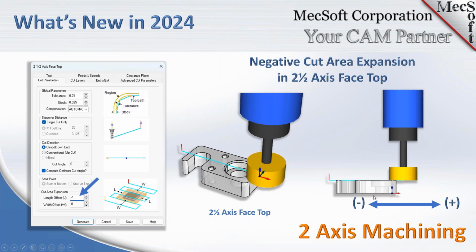Previously, the tool would go all the way past the part and clear the edge of the part. Now, if the tool is sufficiently large, or even regardless of what size the tool is, you can bring that tool in closer to the part by entering a negative value in the cut area extension.